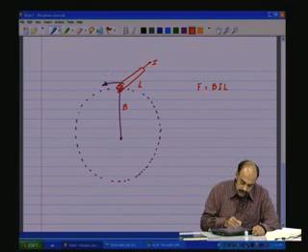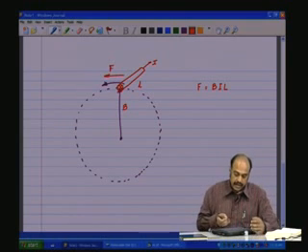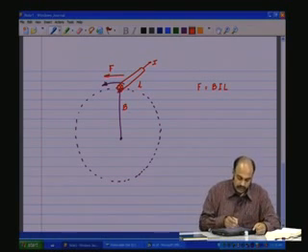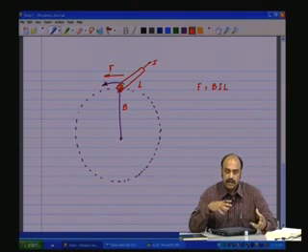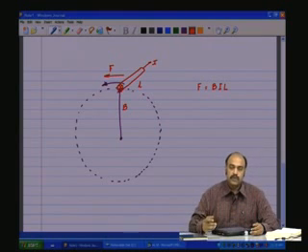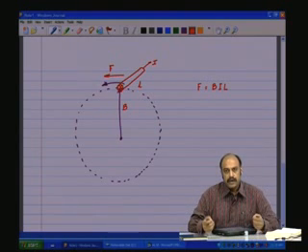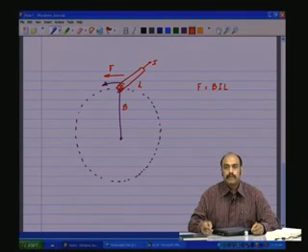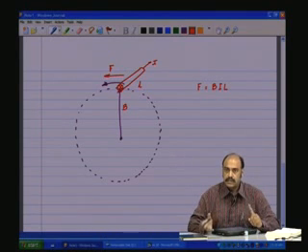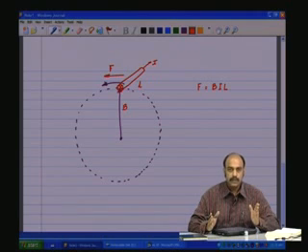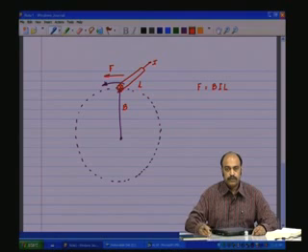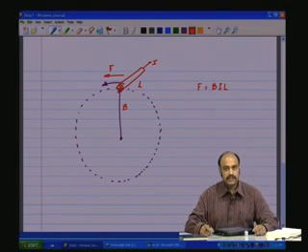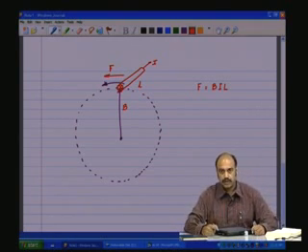So this will cause the conductors to move, and it will try to catch up with the field which is already rotating. Initially, when the rotors are not moving, the field is rotating at whatever the applied frequency, and there is a very large relative speed between the rotating magnetic field and the stationary rotor conductors, and therefore that is going to induce a very large current in the rotors, which is going to give you a huge torque.